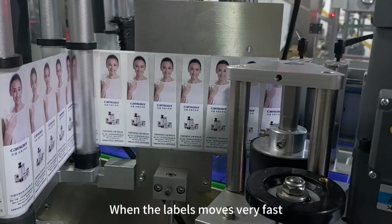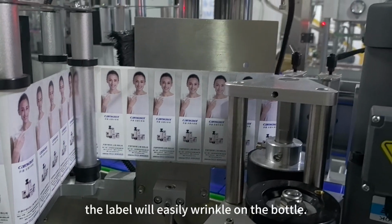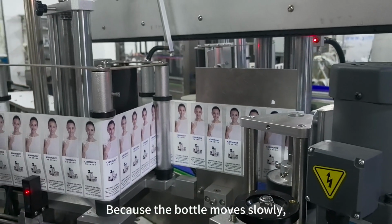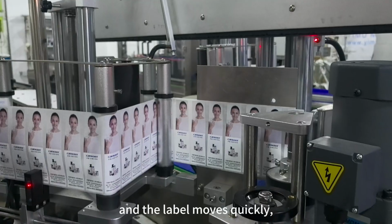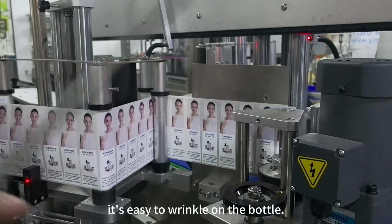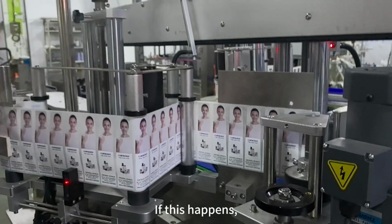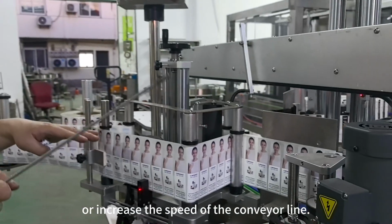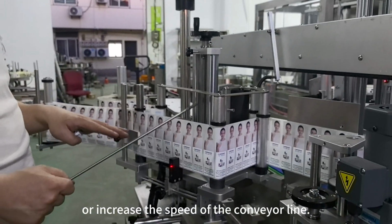When the label moves very fast, the label will easily wrinkle on the bottle. Because the bottle moves slowly and the label moves quickly, it's easy to wrinkle on the bottle. If this happens, we need to slow down the label's move speed or increase the speed of the conveyor line.